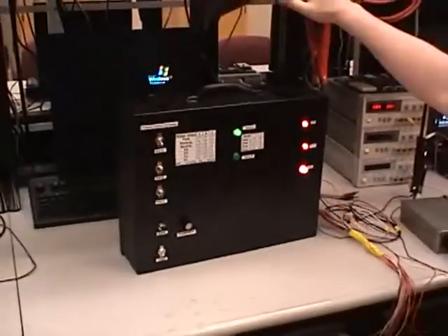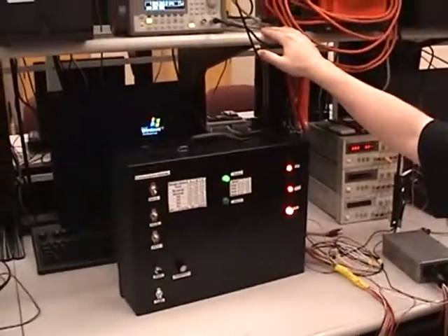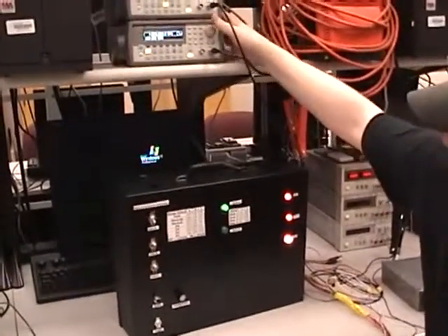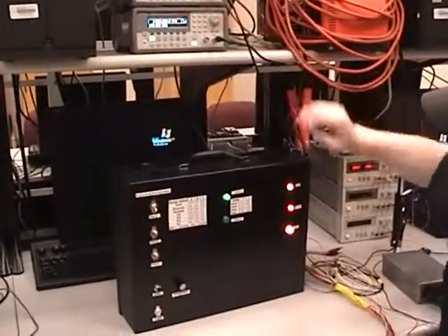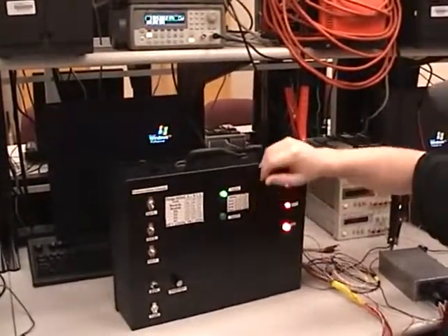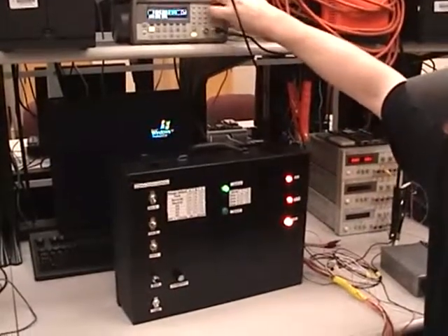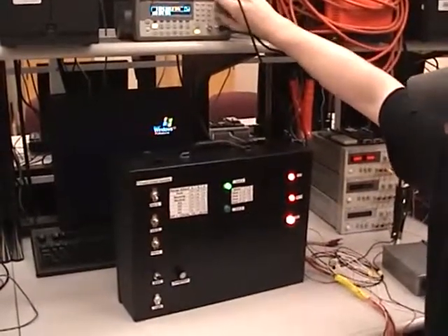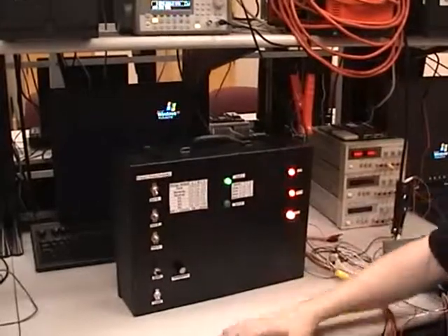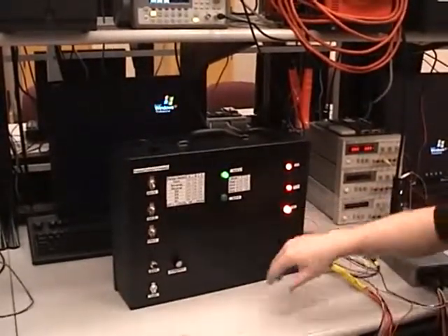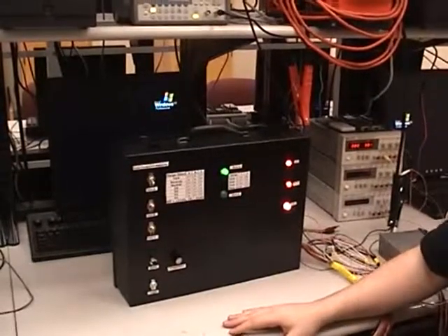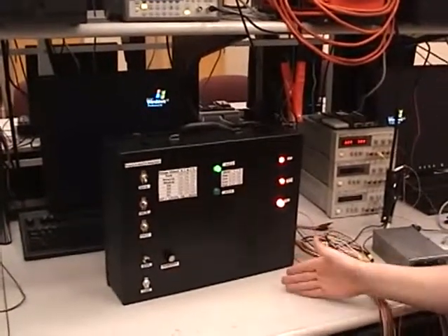One thing that is not implemented in the code right now, that is currently not working, is that any significant change in speed should unlock the TCC. So even if it's in fourth gear and the brake's not detected, if we change the speed and simulate a large acceleration or deceleration, then the TCC should unlock also, so that damage does not occur to the transmission.